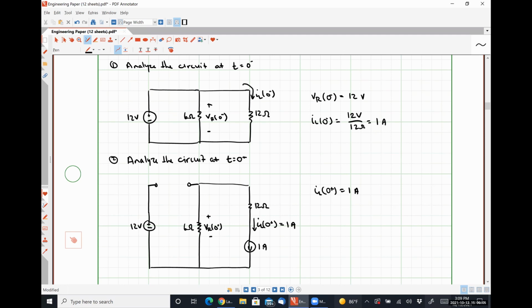So with that in mind, what is the voltage drop over our resistor at t equals 0 plus? So what is VR? Right, that's what I'm looking for, very specifically VR. Negative 6 volts, okay? Because the current makes this corner and starts flowing up into the negative polarity terminal, so the voltage is going to be negative. And 1 amp times 6 ohms looks like 6 volts. So we have negative